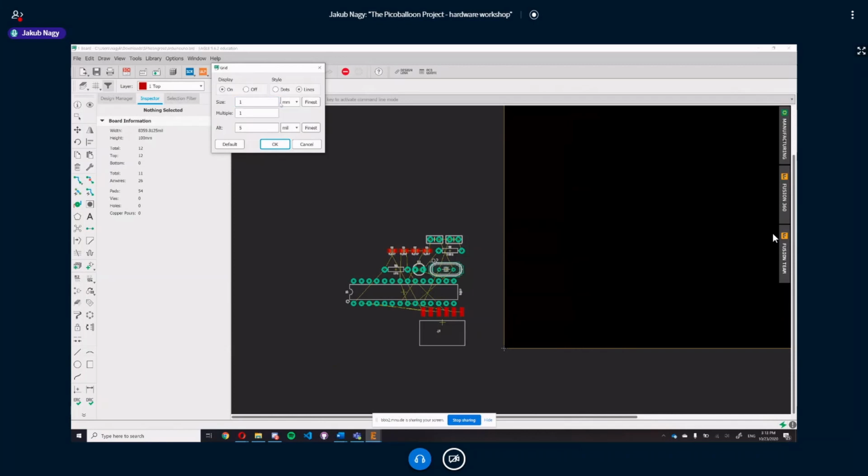So we normally use a millimeter scale for this, while the previous one used inches. So I have 1 millimeter of this normal scale, but when you are working with the board, you many times need different scales. So I also set this to millimeters, and I put, for example, a tenth of a millimeter for now.